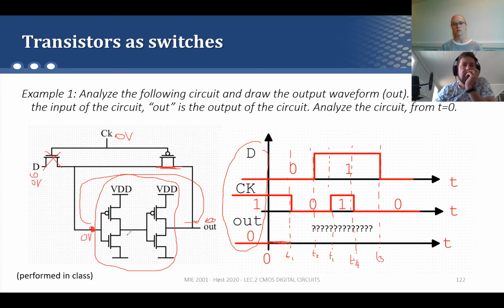And in the middle, there will be VDD. So this inverter forces the output to be VDD, and this VDD forces the output of this inverter to be 0. So practically, in this situation, the circuit does not change. It stores the data in the circuit. So here is 0.